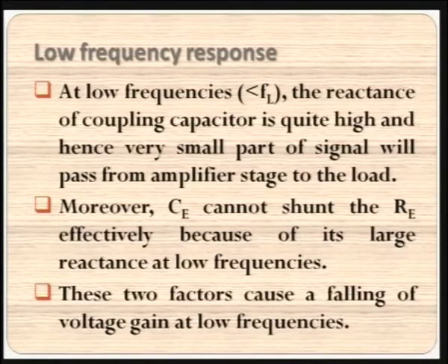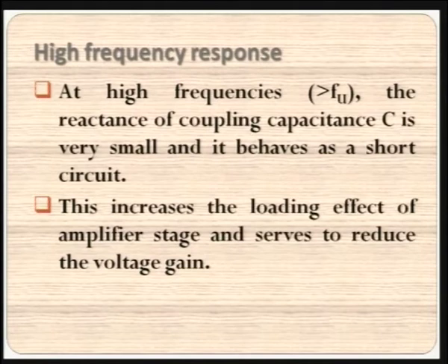But here the capacitor which is on the input side and the capacitor which is connected across the emitter, they offer a huge reactance when the frequency falls, when it is low. So, that is why it is affecting the gain very much. Now, let us see what is happening in the other frequency ranges. What is the reason for the frequency response curve?